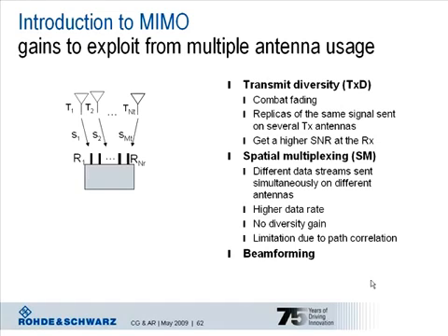The transmission may not always be successful, and this largely depends on the correlation characteristics of the mobile radio channel. If the channels formed between the transmit and receive antennas are highly correlated, then the performance of spatial multiplexing will deteriorate. So spatial multiplexing really works best in uncorrelated scenarios. And we have a high dependency of the performance on the channel conditions,